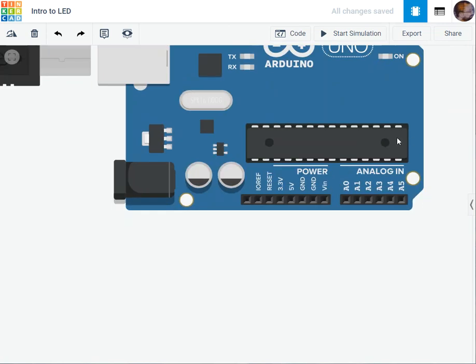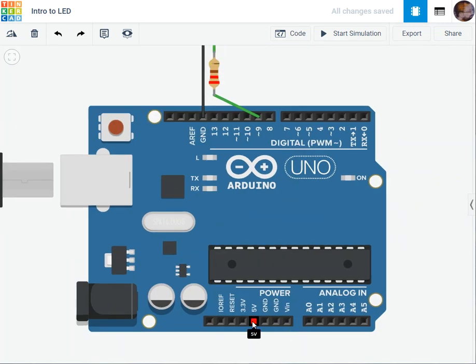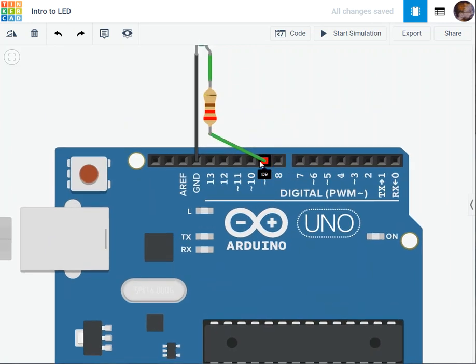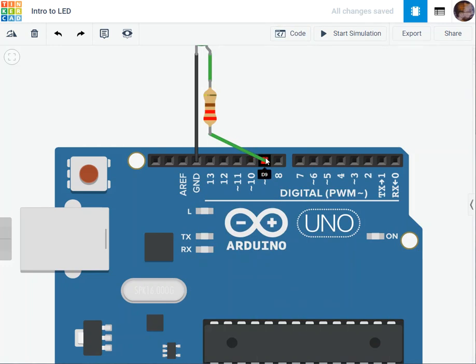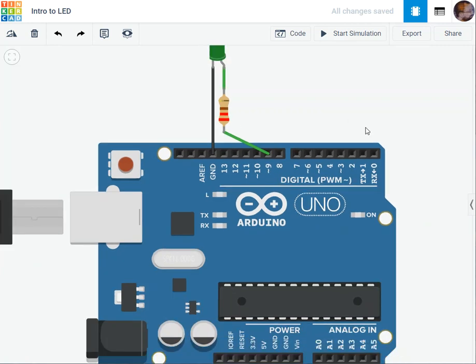What's the difference between the voltage here, where I'm having current, and the current here? The current here is not programmable. It's always there, always supplying me. While here, I can control the gate. I can turn it on and off based on the microcontroller. More than that, I can make it either an output using code, or I can make it an input utilized for a sensor.